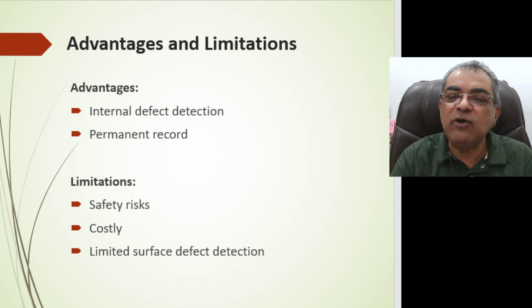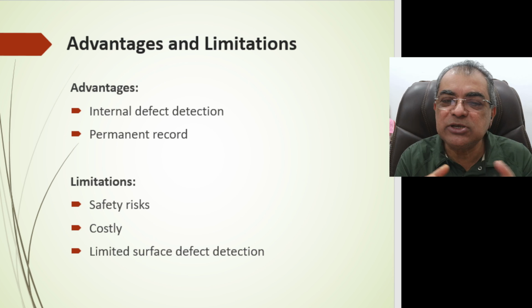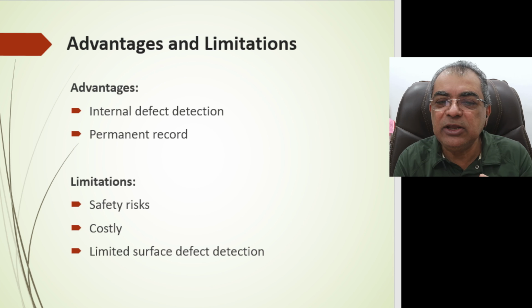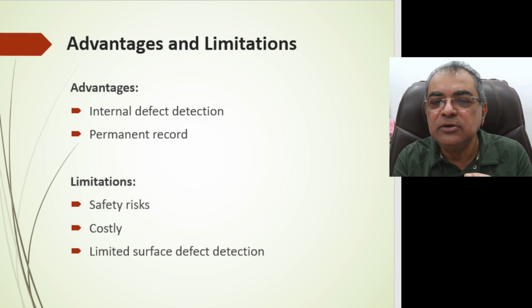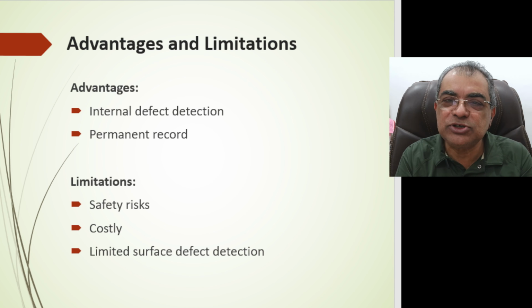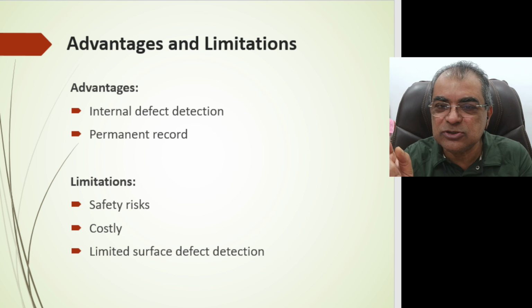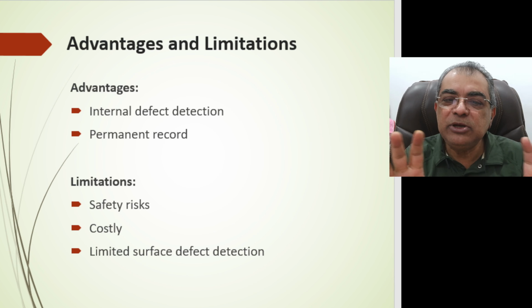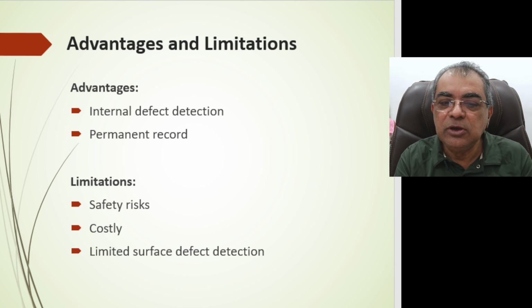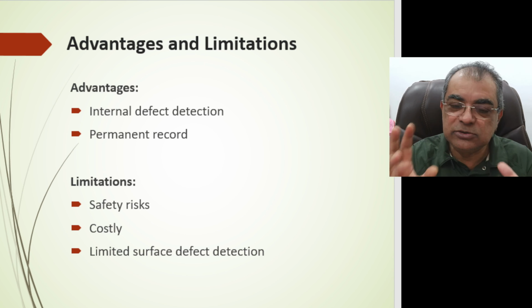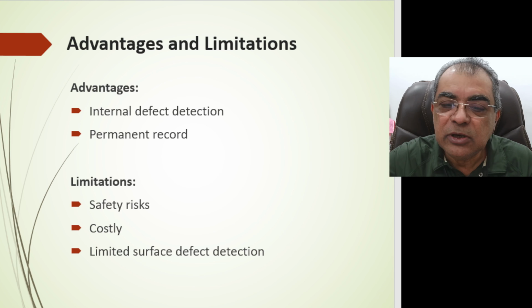These are the advantages and limitations of radiography. Advantages: it detects internal defects, because it is a non-destructive test, always called NDT, and the parameters can be recorded. Limitations: there are safety risks, it is costly to do, and it has limited surface defect detection.